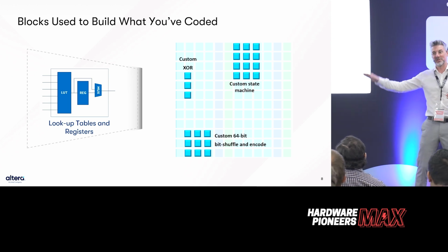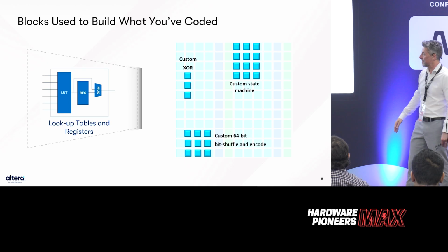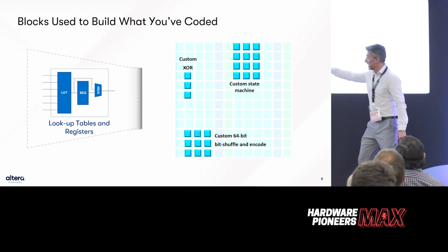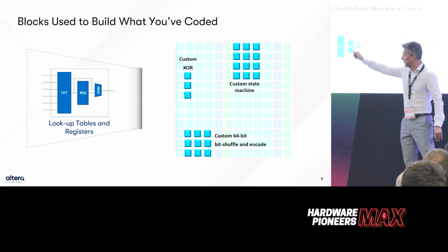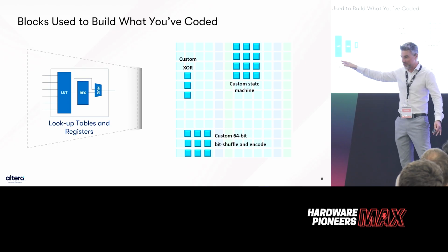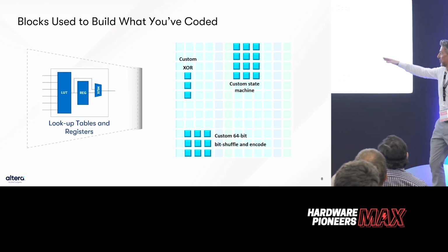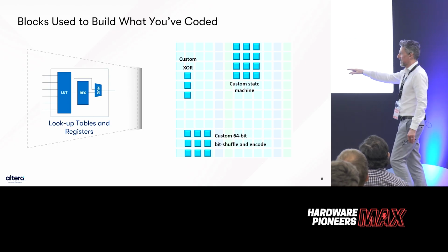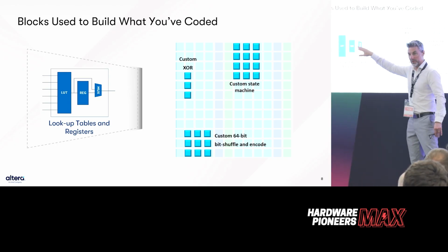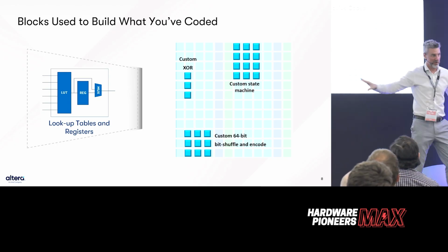If you recall back to your engineering days, a bit of a Boolean logic function. They come in different flavors, maybe 4, 6, 8 inputs to them, but they're all roughly the same kind of thing. You also then get a register, a flip-flop with that, and then some multiplexers. And some of our devices have maybe 2 or 3 registers built around this. So that's the basic building block of an FPGA.